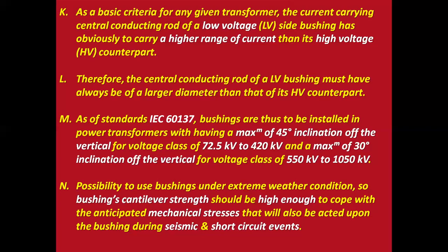Possibility to use bushings under extreme weather conditions. So, bushings' cantilever strength should be high enough to cope with the anticipated mechanical stresses that will also act upon the bushing during seismic and short circuit events.